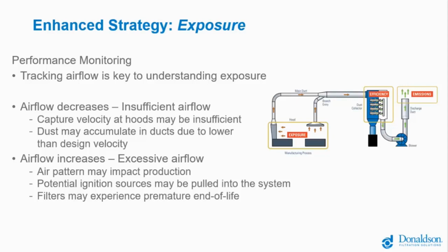You can also have problems when airflow increases. If you do have a process that creates sparks, it becomes more likely those sparks can be pulled into the system where you've got the potential for a fire hazard. And the excessive airflow can also cause particulate to hit the filters at an excessive speed, which causes them to embed in the filters. And that's going to cause premature filter end of life because they can no longer be cleaned with the compressed air.